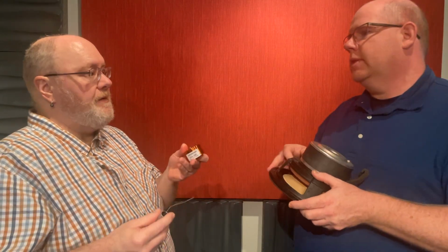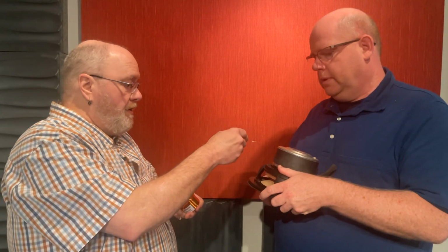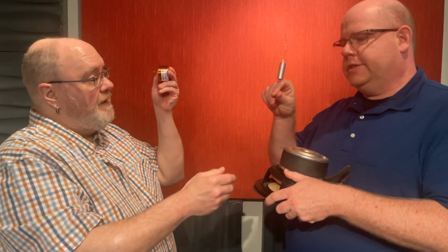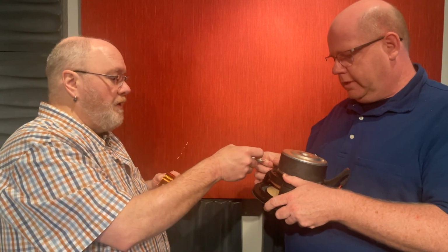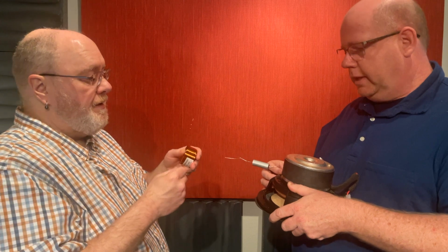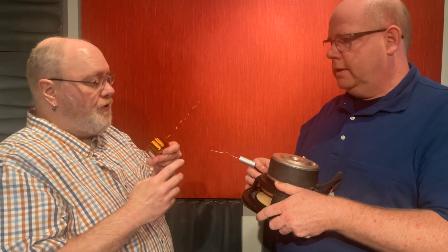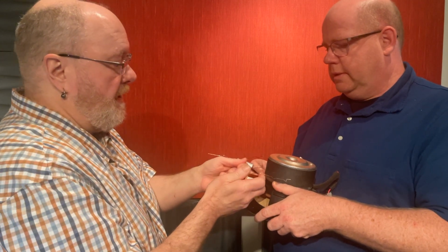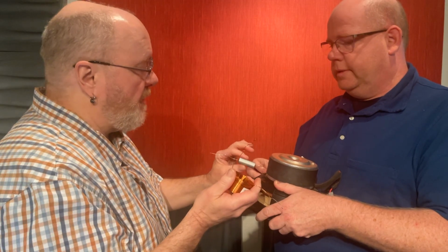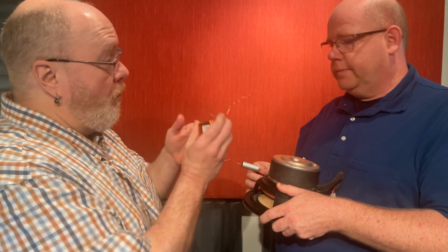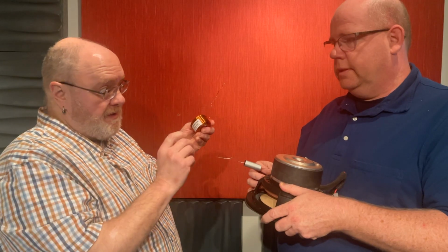But you're probably not going to want to do that going to a woofer. There's a reason why you don't filter with first order filters, 6 dB, single element filters. It's always capacitor for the highs. So this is just another capacitor, a Janssen silver. That's a pretty high quality capacitor. And the inductor, you do not want to just put an inductor like this. It changes things. You want to put the capacitor first, or the inductor for lows on 6 dB per octave.